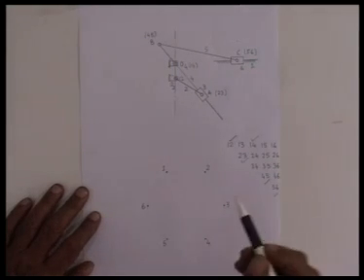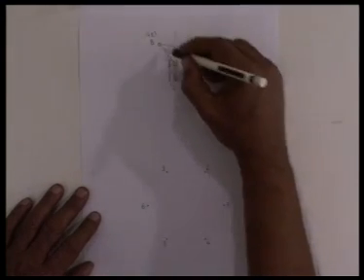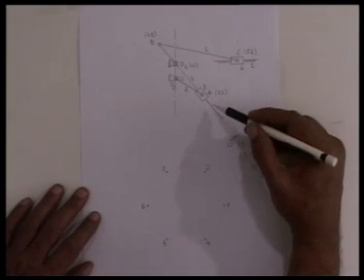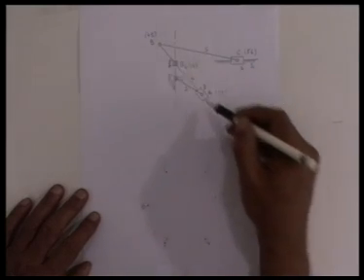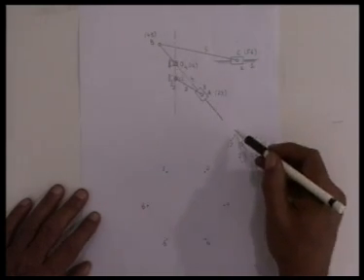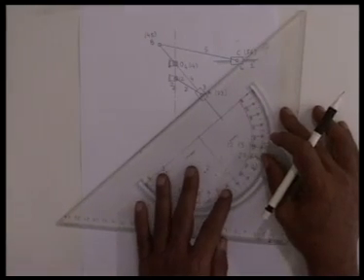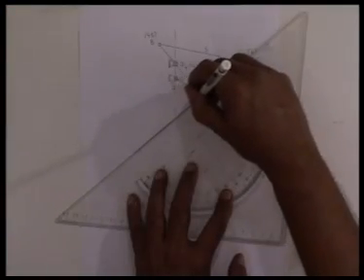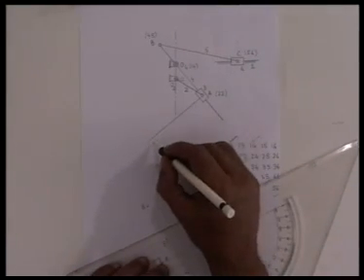The other 2 kinematic pairs in this linkage is a prismatic pair between link 3 and 4 along this slotted lever. So the relative IC 3, 4 will lie at infinity in a direction perpendicular to the direction of sliding, that is perpendicular to the line O4A. So I can draw a line which is perpendicular to O4A, and 3, 4 lies on this line at infinity.